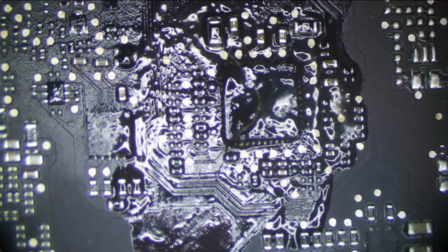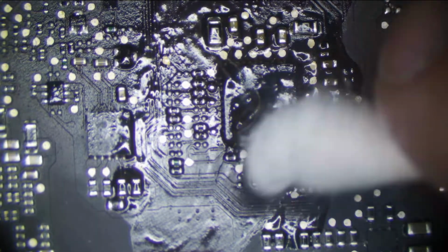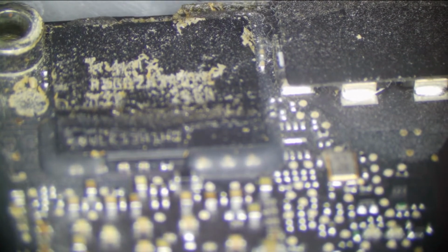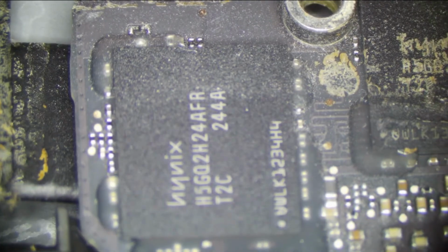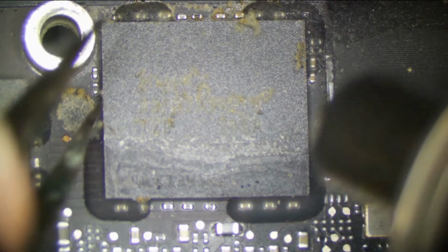Reflowing is okay if you have corrosion or junk under something. That is perfectly fine. That is not a temporary solution. When you have something that looks like this, that has corrosion and junk under it, then it's perfectly fine to heat that up to get the junk out. So what we would do is use some flux and feed the flux under it. The flux is going to dissolve all the junk under it, and if we do a complete reflow on it, then it'll restore any broken solder joints that may be corroded or anything like that.